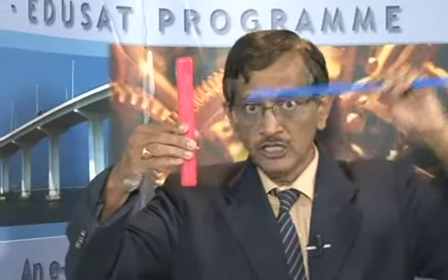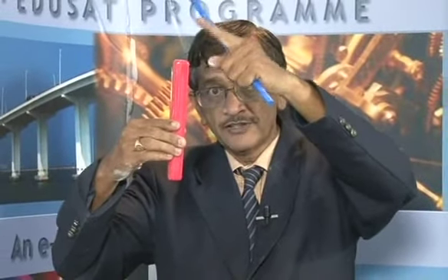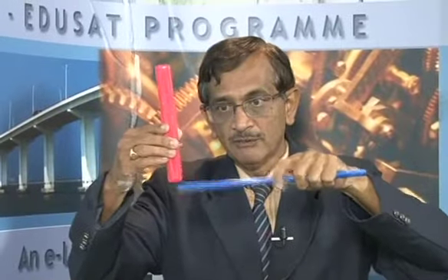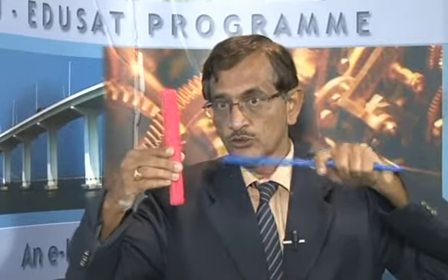We learnt that at the top, when the depth is not there, intensity of pressure is 0 and maximum at the bottom, and it follows a triangular law, correct? Intensity of pressure is equal to gamma liquid into HL, right? After that, we discussed the units of pressure, which is Pascal, 1 Newton per meter square, and 1 kPa is 1000 Pascal. I think you know 1 MPa is 10 to the power 6 Pascal.